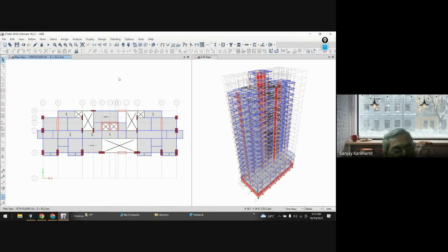The building is not habitual to that, so it will start dissipating that energy. Now, if it is dissipating the energy in torsional mode, then the building might collapse. But if it is dissipating in the translation mode, then the building will be stable.